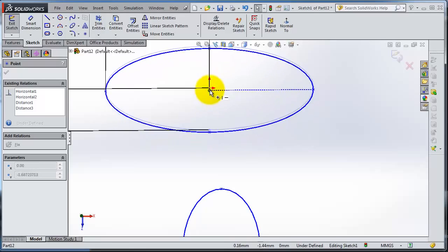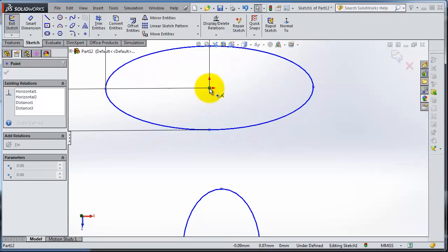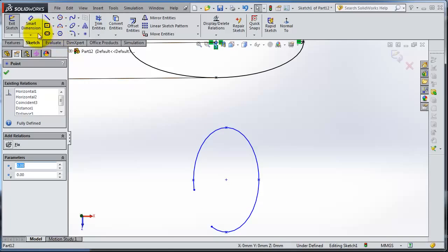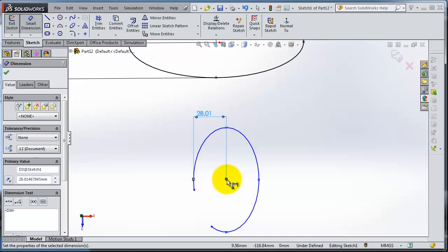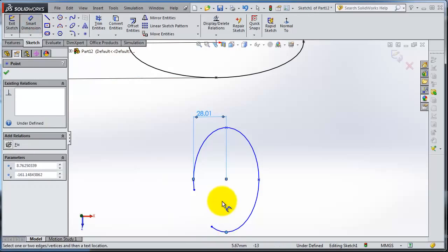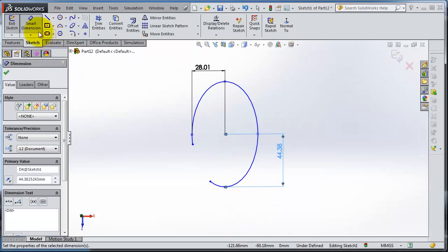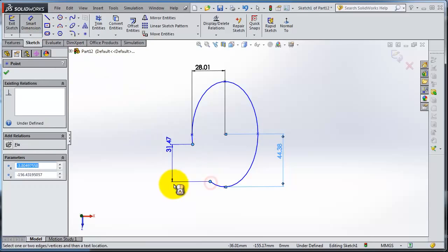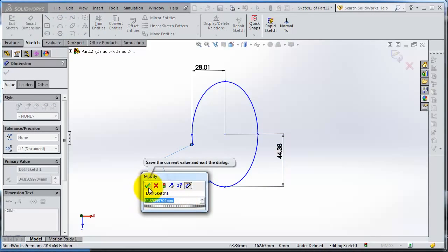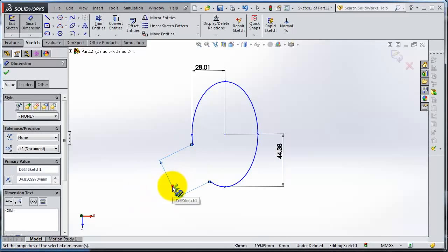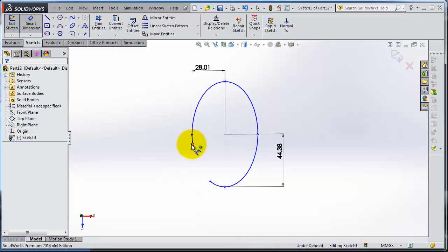move it. So let's move it again and add origin, and you notice that relation is activated. So here you can add dimension in the same way. Second direction, and you need one more dimension, the gap in the partial ellipse. Select these 2, make a gap of 34. Let's delete that. Let's select these 2 points.